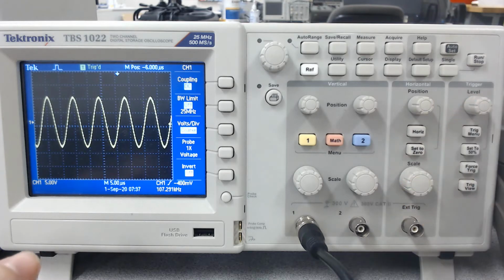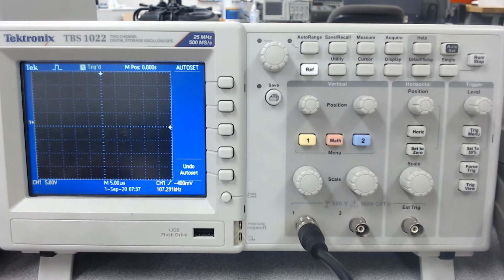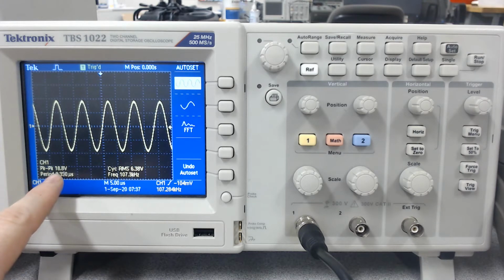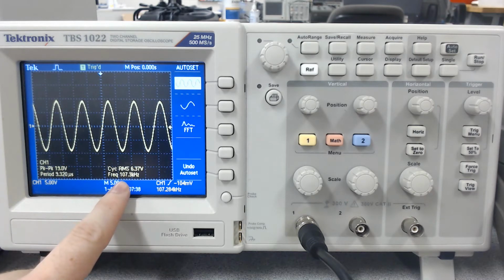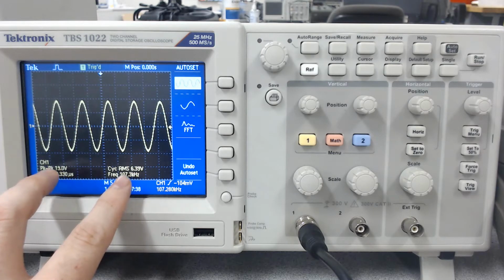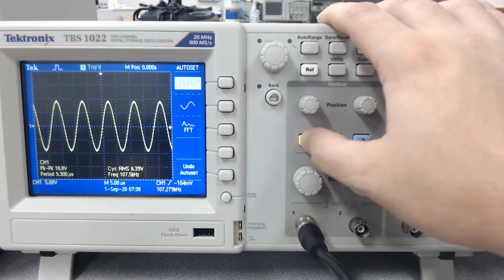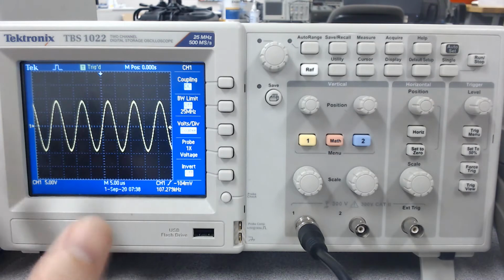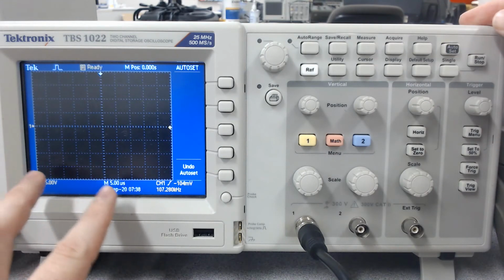That looks pretty good. Just out of curiosity, what we can do at this point is hit the auto set button and see what it thinks would be the correct answer, which was basically what I had there. It might have centered it a little bit more. The advantage of hitting the auto set button is that the peak-to-peak values and frequency that we talked about in the earlier lab videos show up. Sometimes if you're messing around with other things, like if you hit channel 1, those aren't there. So the only way to get those to appear really easily is to hit the auto set button. That's when those will appear.